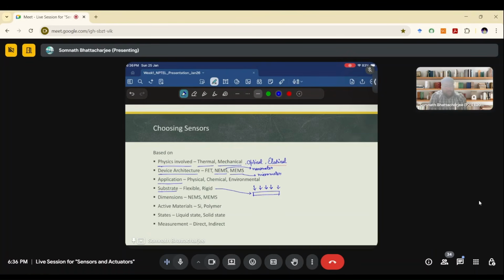Let's say we are making a tabletop sensor or some kind of thing, we can use rigid substrates, like glass substrates or silicon substrates, the conventional substrates, I would say. Why do we need to use glass, for example? In the case of LEDs, or anything that uses an optical input to a sensor, we need glass because it's transparent and it will not block the optical ray, LED, or light. Similarly, for a conformable sensor, let's say we need a sweat patch.